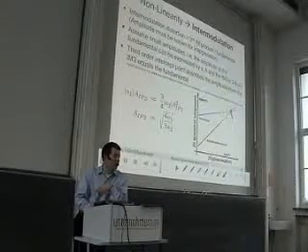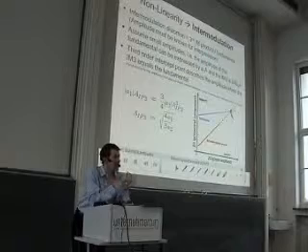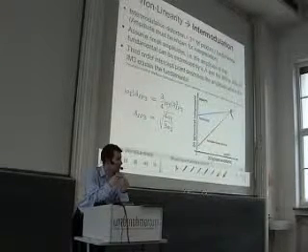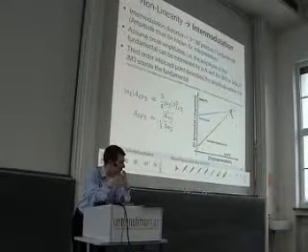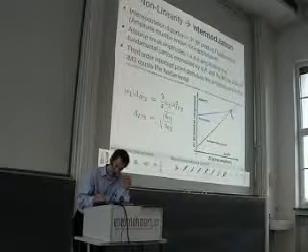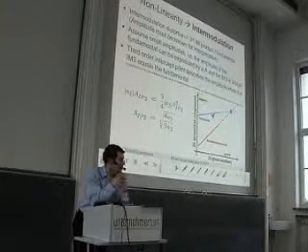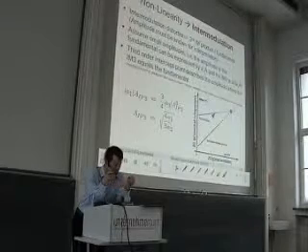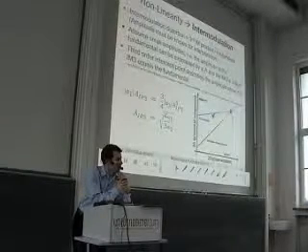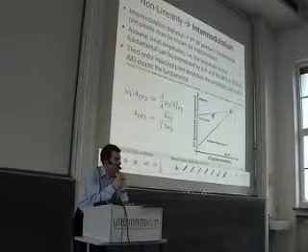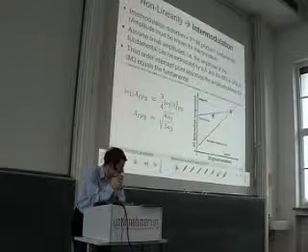Because here at this amplitude, the third intermodulation product would be equal in size to the fundamental. Of course, usually you cannot measure this point because then other non-linearity effects come into play. But what you usually do is to measure the first part here, and then do this extrapolation. By doing this experiment, you avoid that you fall into the trap of frequency selectivity and might assume that the system is more linear than it actually is.